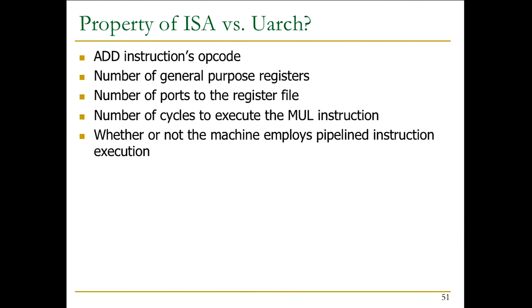Number of ports to the register file. How many reads can you do from the register file? ISA? Microarchitecture? Okay, that's right. This is microarchitecture, at least in most systems, because people don't deal with the ports in the register file. It's usually the microarchitecture's job. But again, you can imagine a system where you specify which port of the register file this instruction is going to use. The compiler can do that. In some systems, yes, you would definitely do that. Some VLIW machines actually expose this.